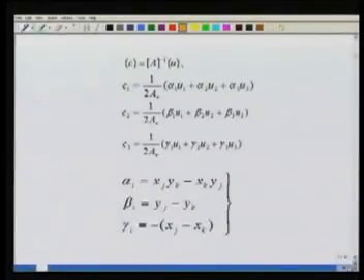So let's now see what we get. The unknown constants C become A inverse into this vector U, and after expanding this out, the constant C1 is 1 by 2 area of the element tau into alpha 1 U1. U1 is the value of the function U at the first node, which has coordinates x1, y1, plus alpha 2 U2 plus alpha 3 U3.